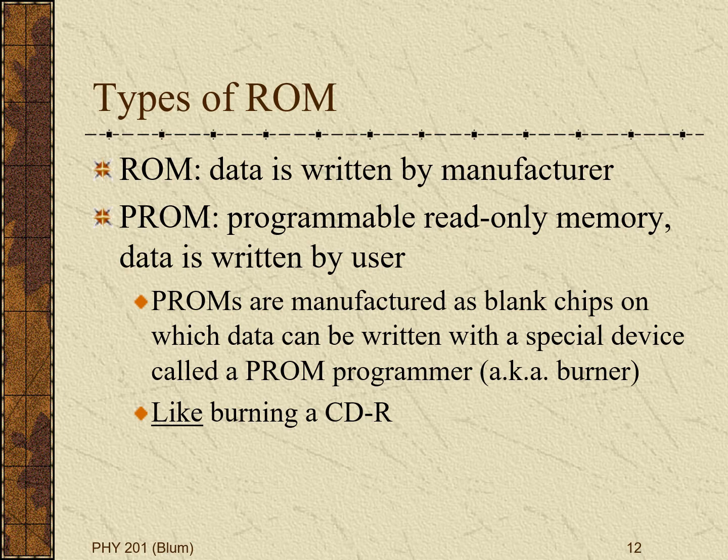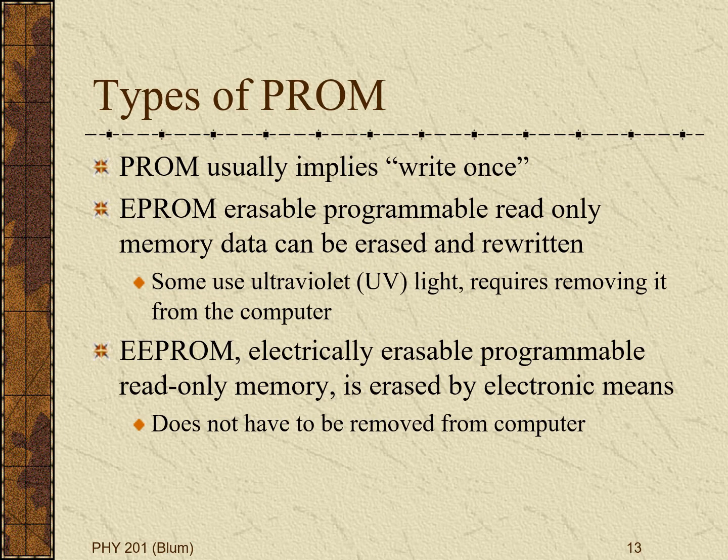So another term for it can be write once, read many. Sometimes it will be called a WORM. And so it's like a CD-R. You have some special way of burning it, so it's a blank CD, and so you will write something onto it, but after that it is only read. So PROM, Programmable Read-Only Memory, was written to once.